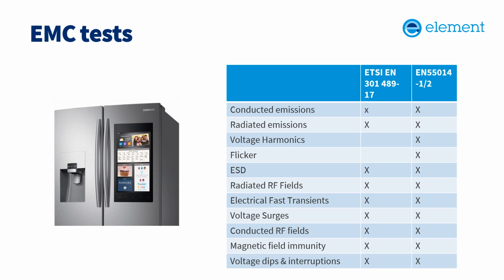And you can see that essentially all of the tests are repeated. One is looking at the effectiveness of the fridge? How does it maintain the functionality of the fridge? And the other one, the ETSI 301-489 standard, is making sure that the radio characteristics, it doesn't drift off frequency, doesn't stop transmitting or receiving information, the data rate isn't affected. That's the job of the ETSI standard.